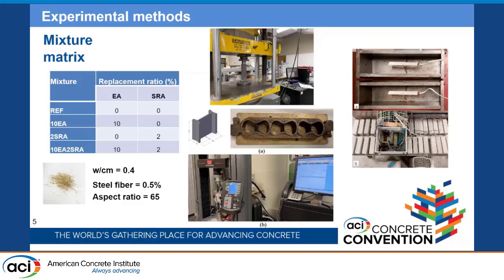You see in the middle the compressive strength and fiber pull-out strength testing process and equipment. On the right, I use embedded strain gauges, which enabled me to measure the shrinkage immediately after casting while the concrete was fresh and up to the end of the experiment.